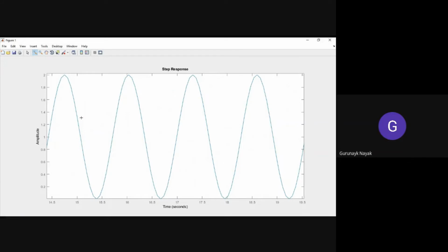Are you able to link everything? Okay, I repeat again, slowly. You have a mass spring damper system, MBK system, whose transfer function I had written. In that, if you assume zeta equal to 0, the b by m term will become 0. I hope everyone is following, because we had s square plus b by m s plus k by m in the denominator.